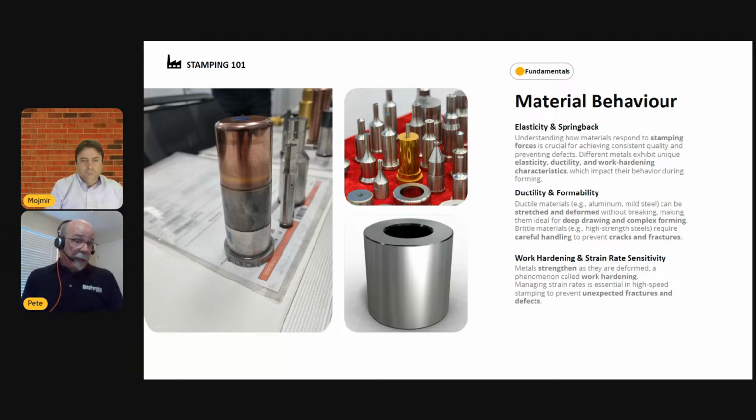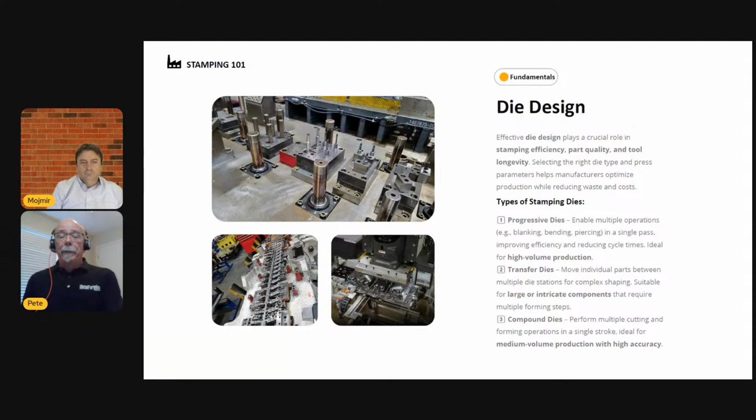Now, aluminum, on the other hand, because of its negative strain rate sensitivity value, has a negative M value. As I form faster, the material gets weaker and more likely to fail at higher speeds. So these are parameters that we have to understand.